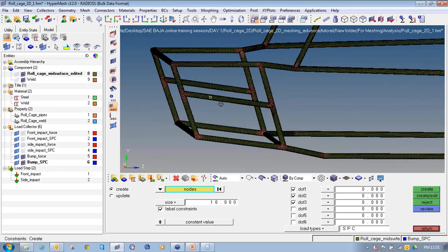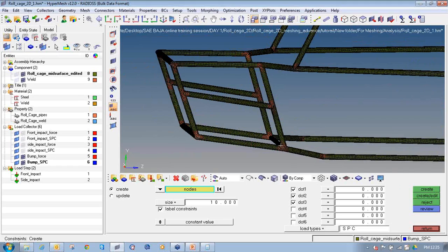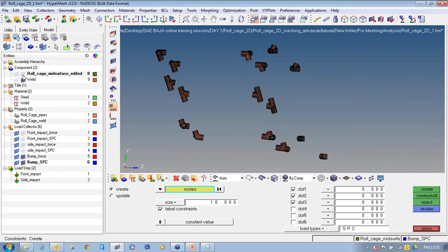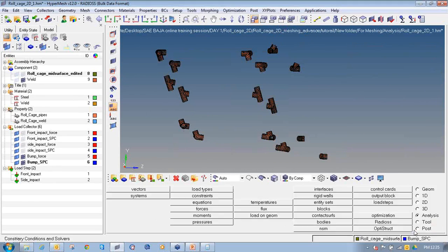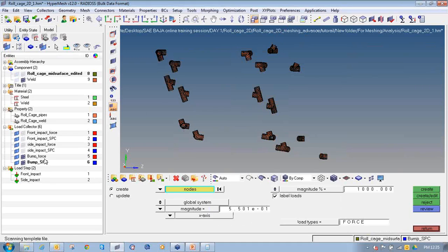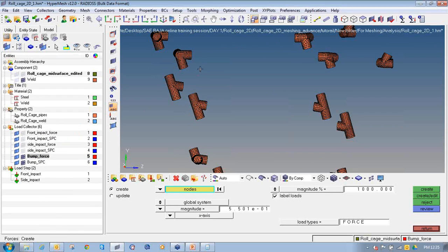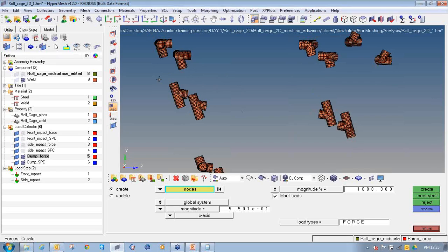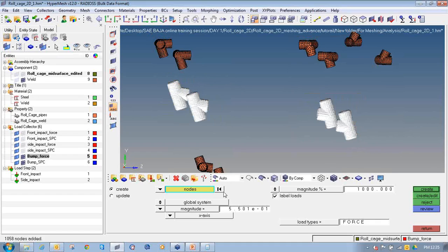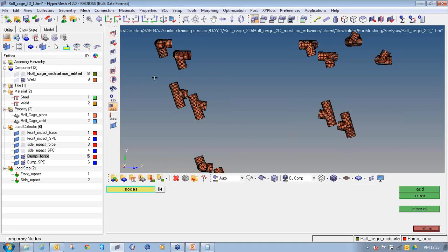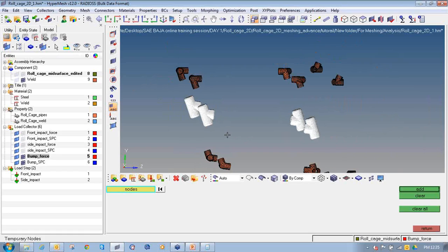And now we will apply the forces on all the 8 suspension front points. So first I need to calculate. Go to analysis, forces, make bump force the current component, so the forces will move towards that. Then turn on, select the nodes, or go to shift F2, add these nodes, select all the nodes.